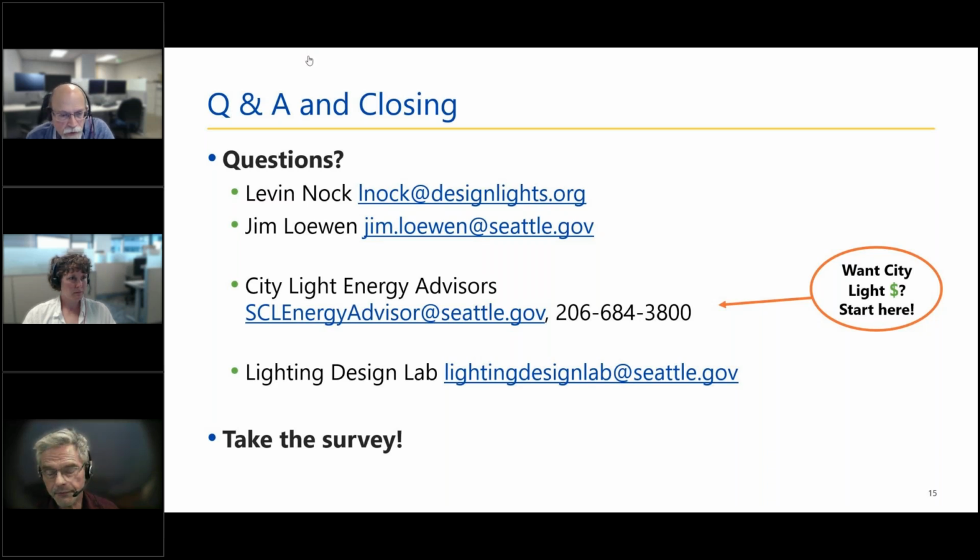Yeah, there's different strategies. Some buildings put everything on a single Ethernet, but then they also segment off parts of it where there's firewalls between different building systems. Other systems really have two networks, where there's one network for the operational tech and a separate network for the building tech. So there's different ways to do it. It just depends on doing something to make sure you're covered well for cybersecurity.